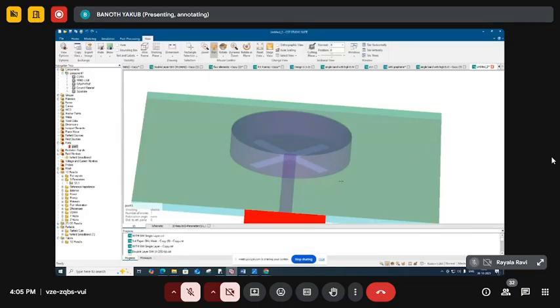These are the bands achieved, and we can also see whether the bands are matched in axial ratio or not. We have seen in post processing that the theta angle is 90, and the phi angle variation we can change from 0 to 150 degrees.